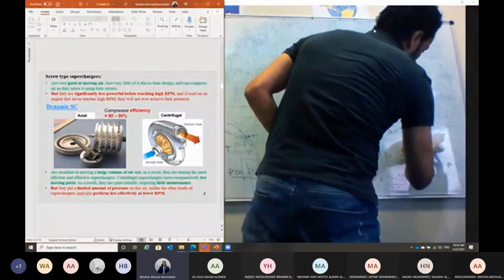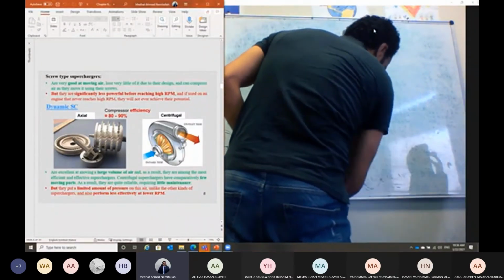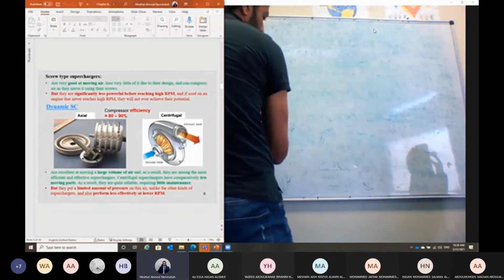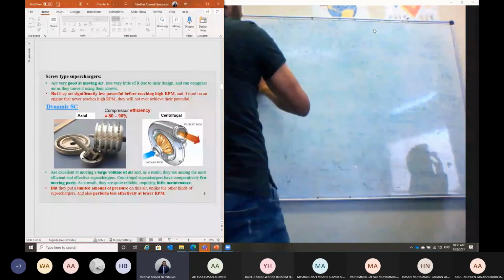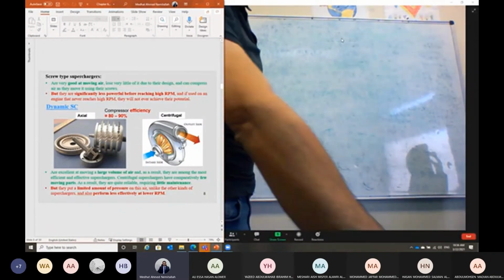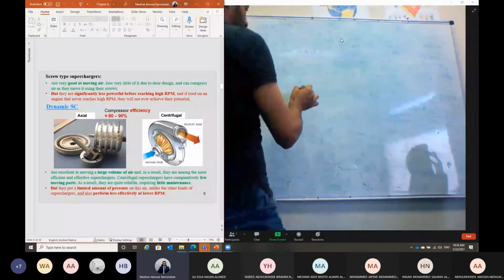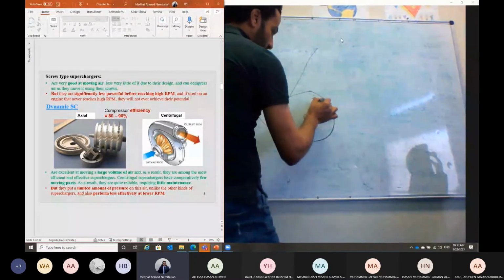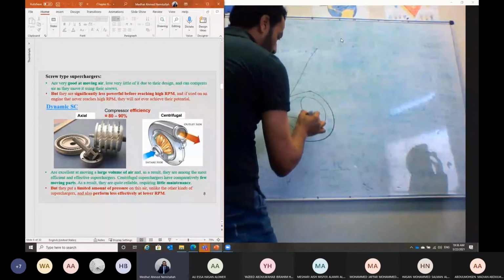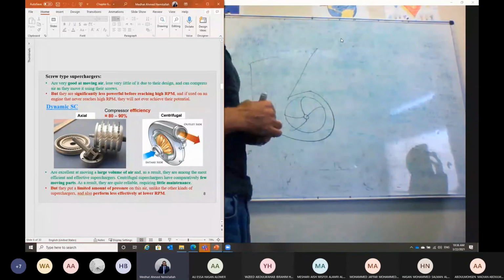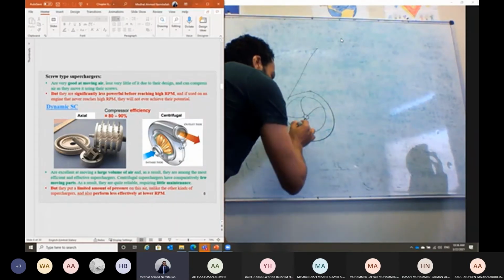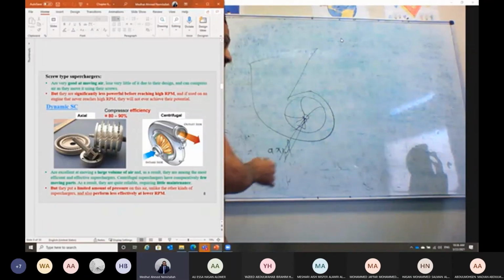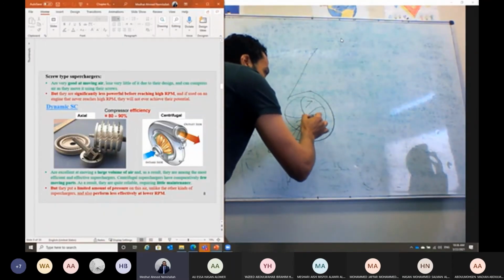So the idea here is to design the compressor, centrifugal compressor, or even the axial flow compressor, with a diffuser shaped flow design. Then we can generate flow pressure. If you look at the centrifugal compressor, usually we have the impeller, and inside this impeller we have the blades. Usually the flow is coming in the axial direction to this centrifugal flow compressor, and it will be leaving through the area between the blades.